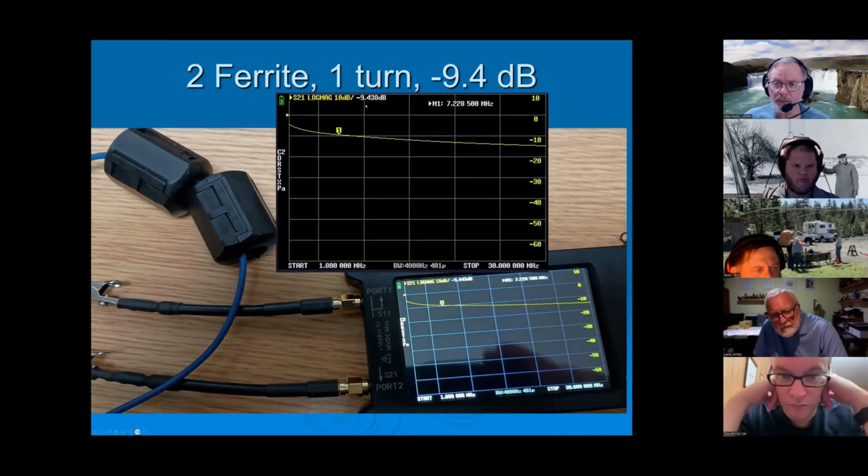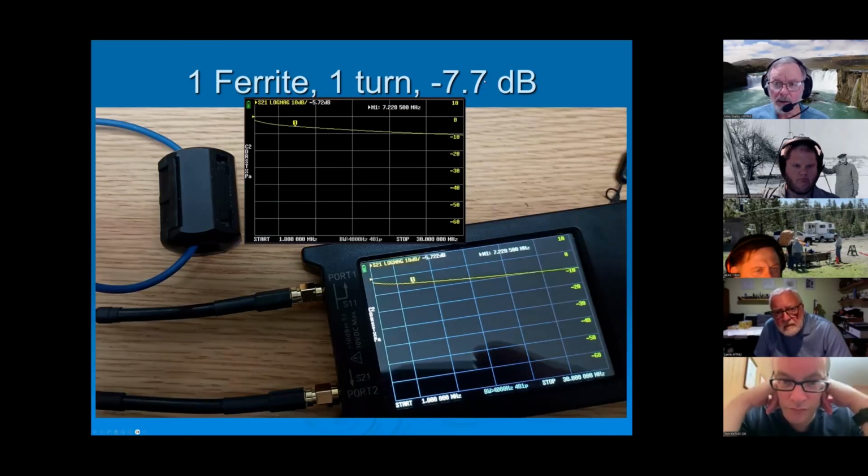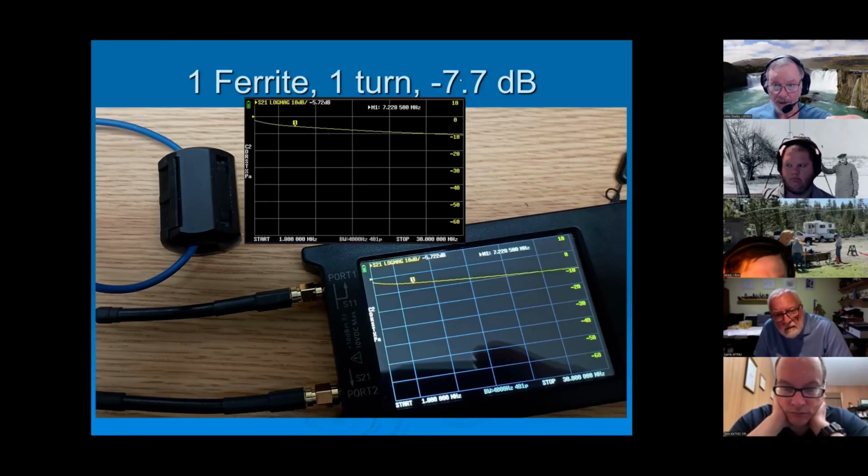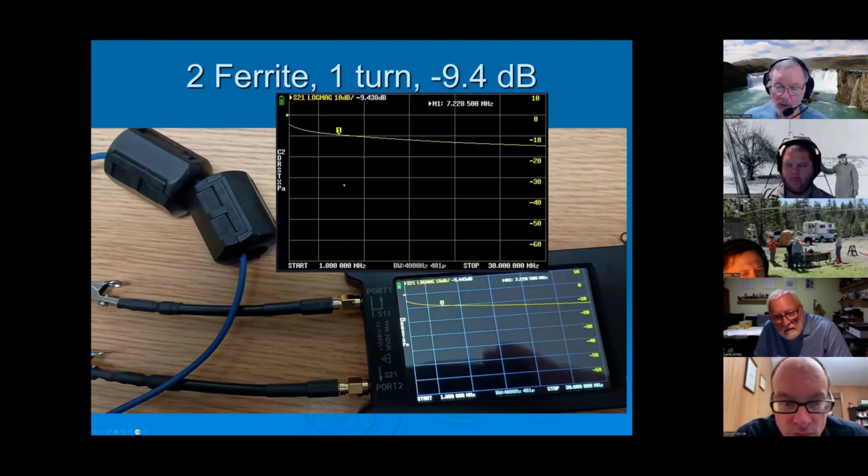Did I say something? I think I said something backwards. No, this is wrong. It's wrong on what I have up here at the very top of it. It should have been the loss of 5.7 dB. So that's a loss of 5.7 dB off of the 0 dB reference. So we're always going to the negative thing. So I screwed up on the labeling up at the very top. Mind you, this is the first time going through these slides, so you know me, I'll have some errors in here.